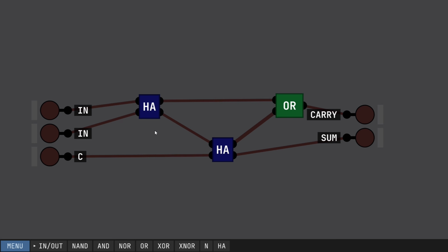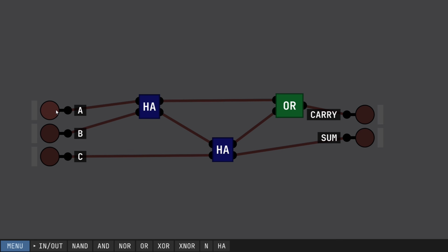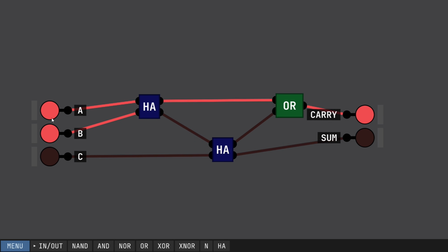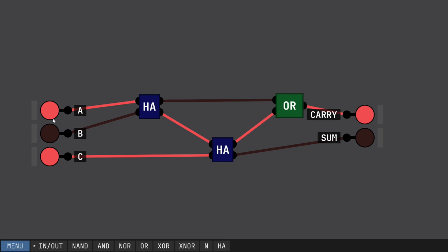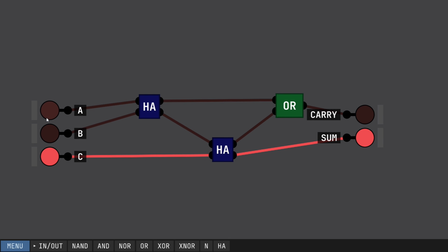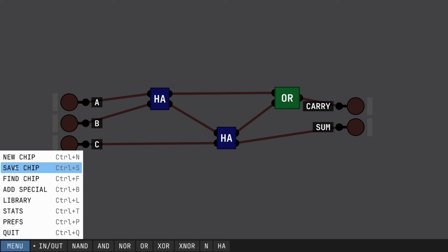And we're going to demonstrate it after I rename all of these pins for our convenience. So we have 0 plus 0 is 0, 1 plus 0 is 1, 0 plus 1 is 1, and then 1 plus 1 is 0, 1. Now if we have this carry on too, it kind of acts like another input. And so we can essentially get the same outputs as this, which allows us again to add our carries to our previous calculation. So we can save this as our full adder.